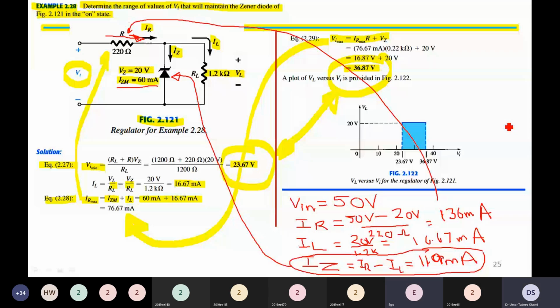Of course, when we use a voltage of larger value, the current flowing through the Zener diode will exceed 60 milliampere. This larger excess current will flow momentarily, and after that the diode itself will be damaged permanently because we have passed too much current and too much power has been dissipated.